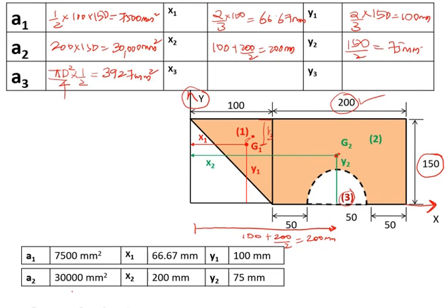So if I mark the centroidal axis here, it is somewhere here. So the total distance is from here to here. From this portion to this portion it is 100, then another 50 plus 100 by 2, because this is a symmetrical section, so centroid will be exactly here, that is 100 by 2. So the total distance is 150 plus 100 by 2, that is 200 mm.